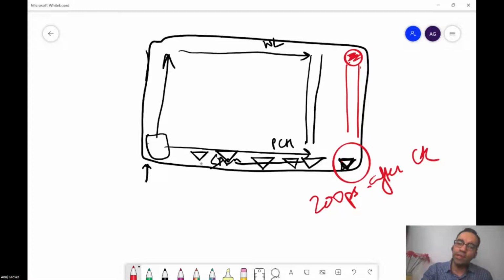So what you want is that the enable signal for this sense amplifier may come early, but for this one it should come at, let us say, 450 picoseconds, when sufficient offset is available at it.